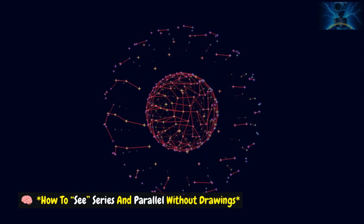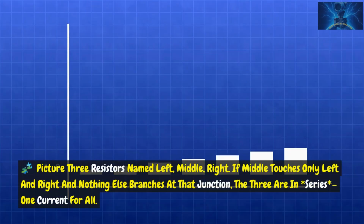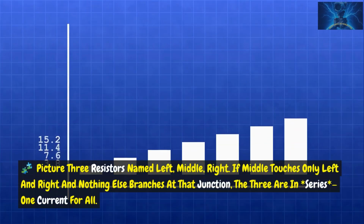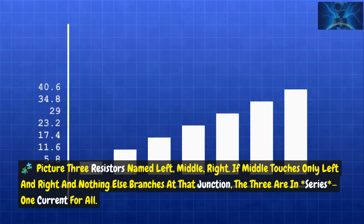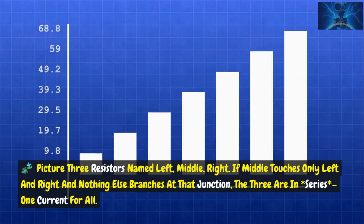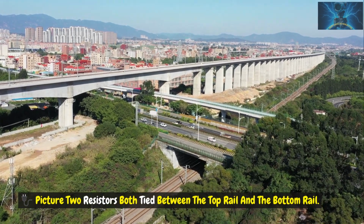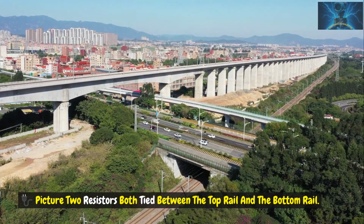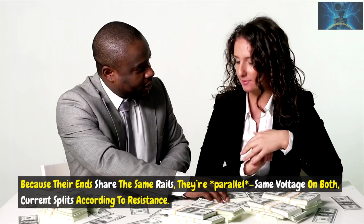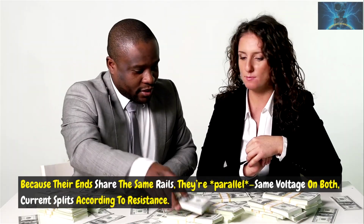How to see series and parallel without drawings. Picture 3 resistors named left, middle, right. If middle touches only left and right and nothing else branches at that junction, the 3 are in series. One current for all. Picture 2 resistors both tied between the top rail and the bottom rail. Because their ends share the same rails, they're parallel. Same voltage on both. Current splits according to resistance.